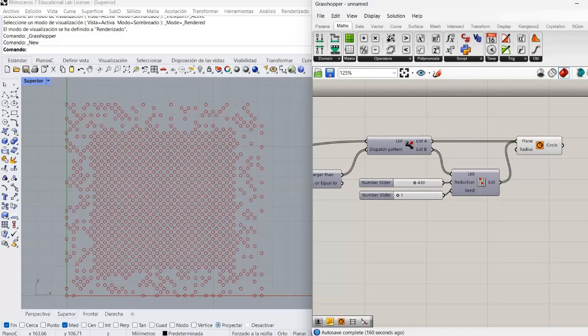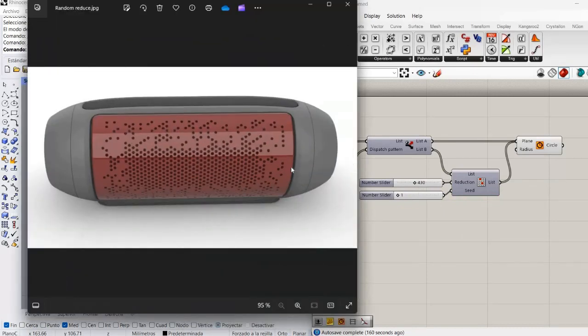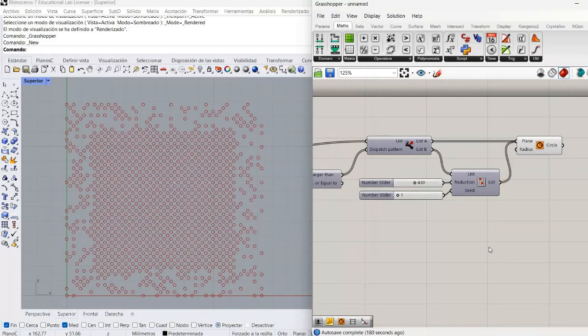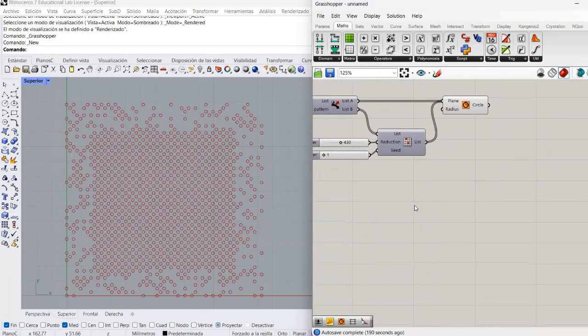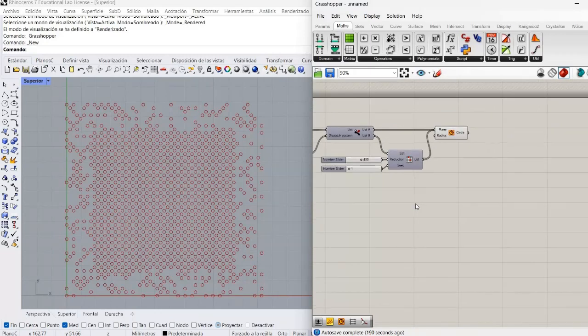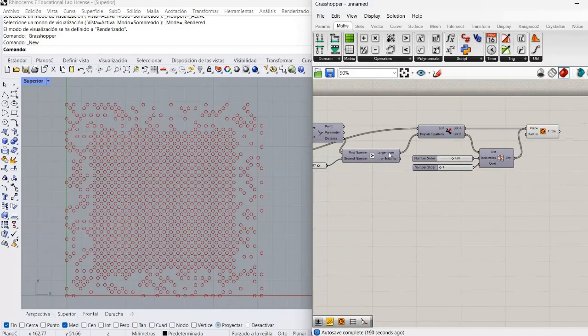The only thing that we have to keep in mind from our design is that we don't want those numbers to go too close to the edge of that surface. That's going to give us some trouble, okay? And actually they need to stop appearing at some point, okay? So what we have to do is we need to create another curve attractor, another conditional like this one, okay, but with the outer numbers or the outer points of this section here.